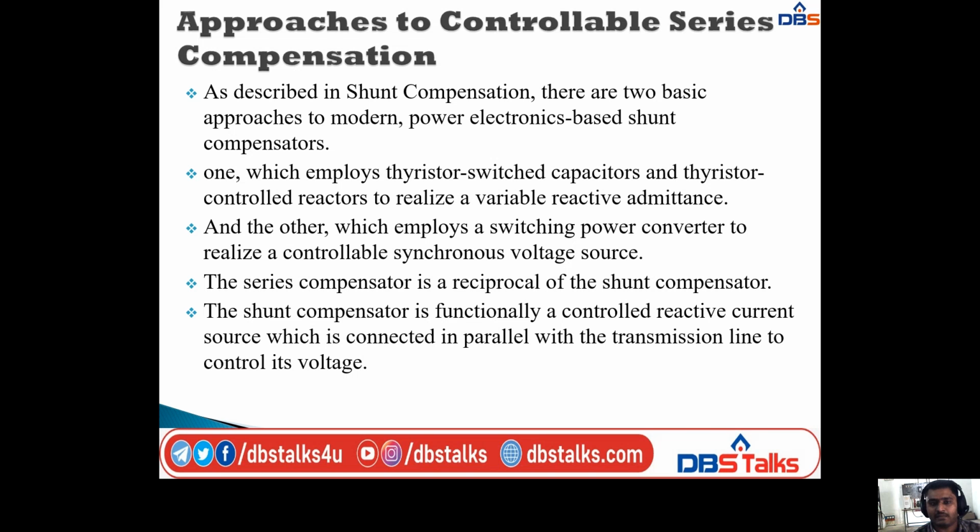In the previous chapter, that is shunt compensation, we discussed two basic approaches to modern power transfer shunt compensators. The first one employs thyristor switched capacitors, that is TSC, and thyristor controlled reactor, that is TCR, to realize a variable reactive admittance.